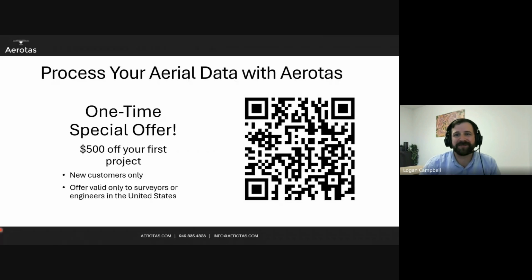We have ones that are bright pink and black. The pink washes out and the black absorbs the LiDAR. So you can usually see it pretty well in both a colorized point cloud and an intensity-based point cloud, depending on your flight altitude and flight resolution. That usually works best. Some companies like using really big 3D ones, that sort of thing.